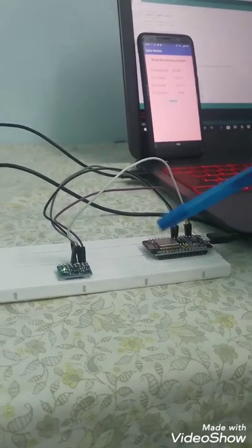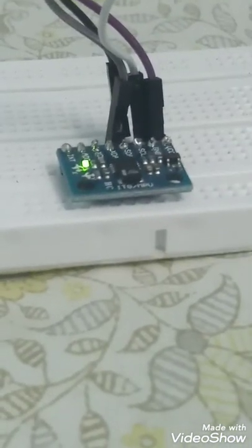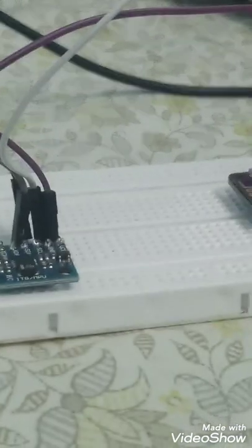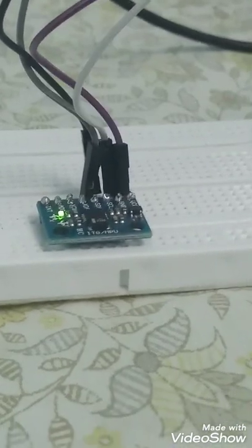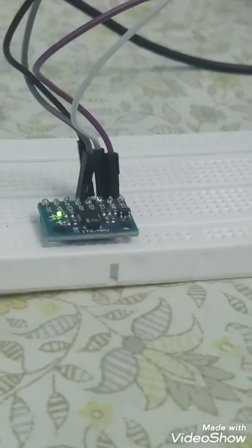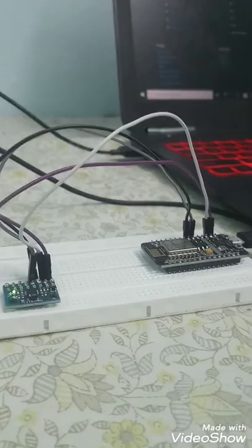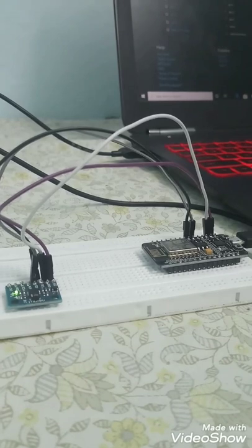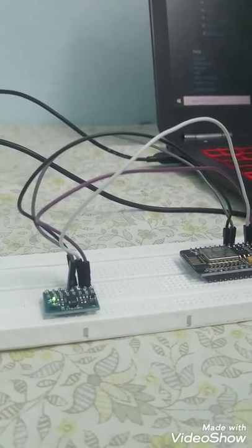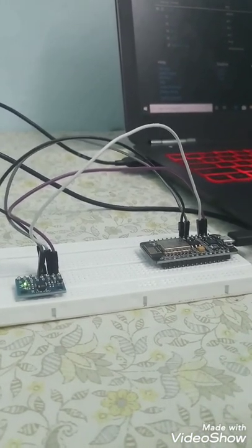So we have used the MPU 6050 gyroscope sensor. The function of this sensor is to maintain and control the position, level or orientation based on the principle of angular momentum. This sensor detects the roll, pitch and yaw motions of the baby in the cradle along the three different axes, that is X, Y and Z. This sensor also provides temperature readings, which is embedded into the gyroscope. With this temperature sensor, we are collecting the data of the room temperature at which the baby is currently present.